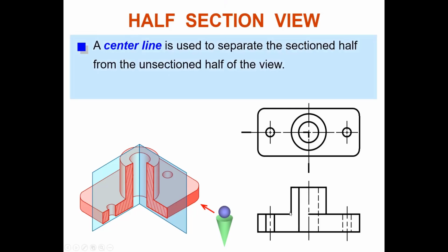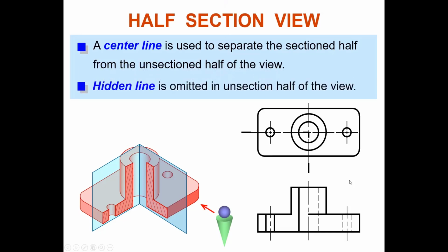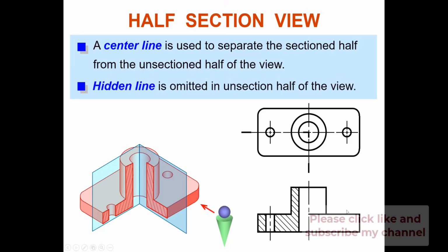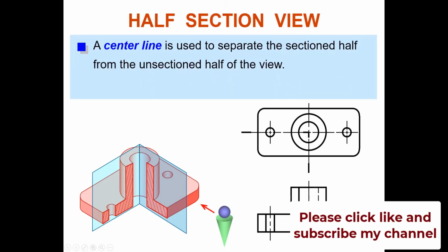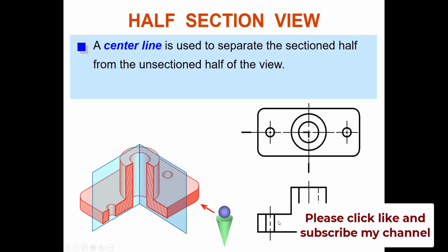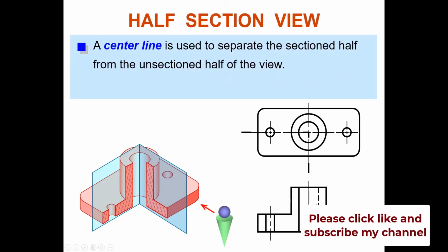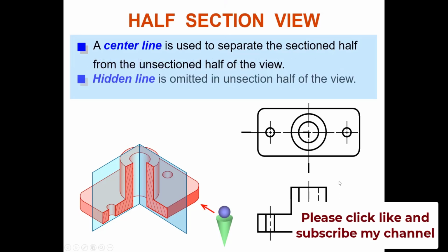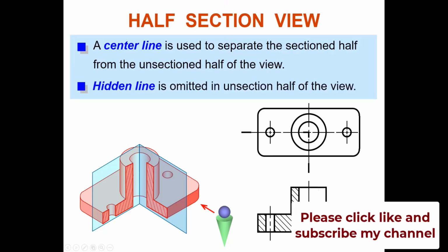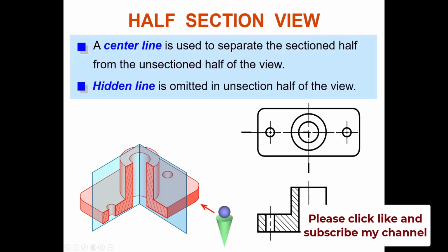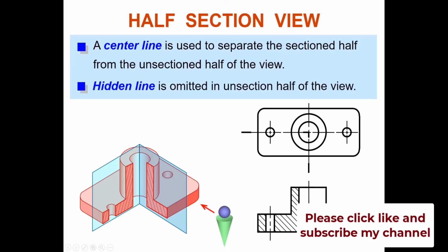Yes. If you look at your front view, can you see the other half? On the right is the typical orthographic drawing, but on the left side you do section. Sorry guys, my mistake. On the right, no hidden line. Be careful. Before this, you thought, sir, because I only do sectioning on the left side, on the right side I will do with hidden line. No. On the right side, you view only the outline of the visible line, no hidden line.